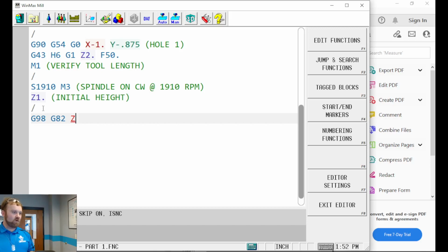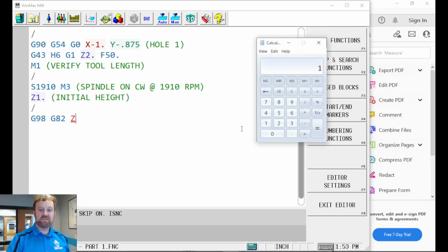On page 24, you see at the bottom it says hole chamfer depth formula. It's a 90-degree spot drill, so there's a 90-degree option. It says 0.5 times the chamfer diameter equals the point depth. Our hole is going to be a 1/4 inch, and let's say I want a 20 thousandths per side chamfer. So I would add 40 thousandths, because that's what the top of my chamfer needs to be.